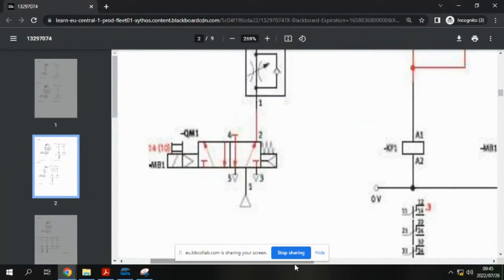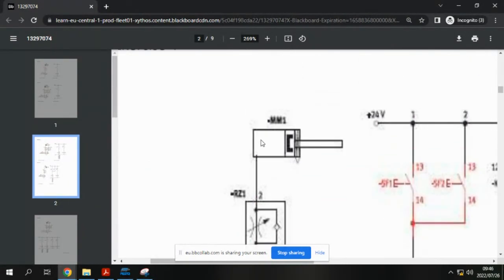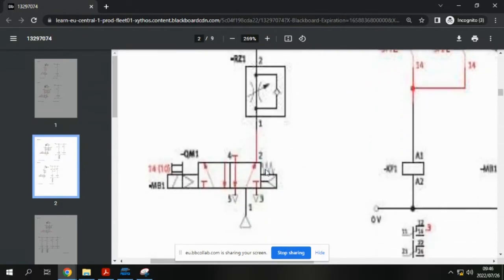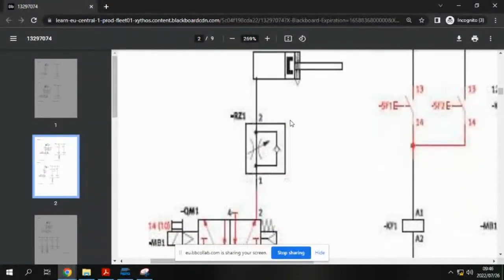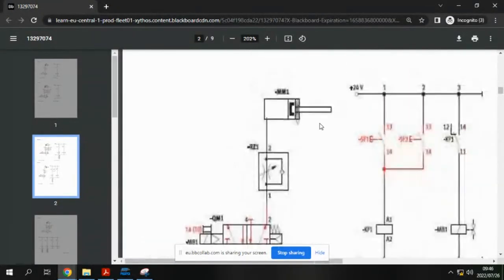The software doesn't allow us to customize, so they use the 5/2-way valve. And I always said it is best to use a 5/2-way valve. So on a normal 5/2-way valve, when you actuate it, it will change from 2 to 4. But now they've blocked 4, then they've let 2 function. Remember, 2 is designed to keep a double acting cylinder in its retracted end position. So they use 2 to push the cylinder forward.